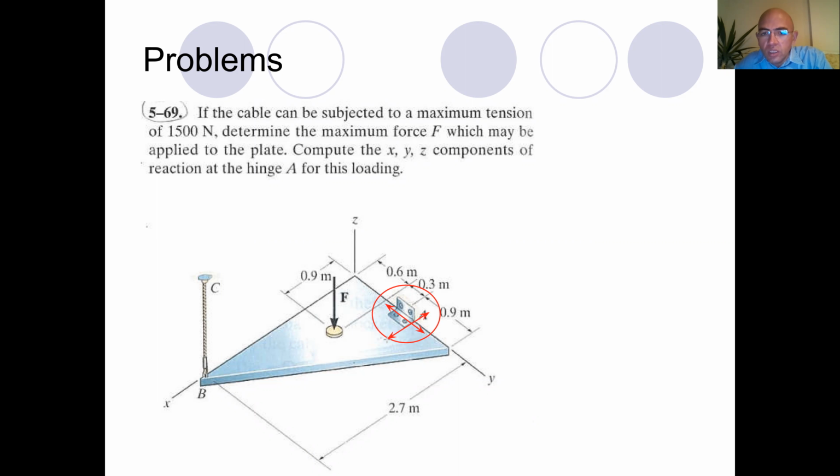Of course, it cannot move in x direction, so in both positive and negative x direction. As a result, there will be a reaction force in x and y direction. In fact, identically, hinge does not allow the motion of the plate in z direction.